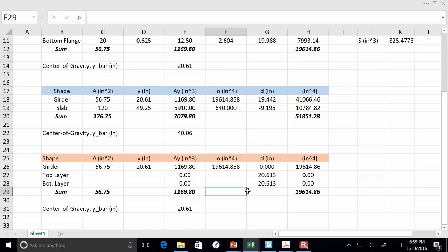Now the nice thing about these computations is we got to determine three things: the area, the centroid, and the moment of inertia. I can do the moment of inertia really easily. I propose to you that the moment of inertia for these two segments is 0. Okay? The reason why is because what I'm doing in this section is I'm assuming I've got this massive amount of rebar lumped into this really, really small space. And I'm asking, well, what's the moment of inertia of this one little piece of rebar right here? And I'm going to assume 0.